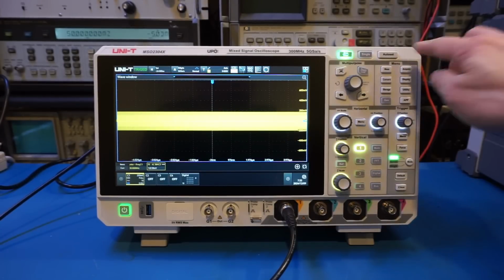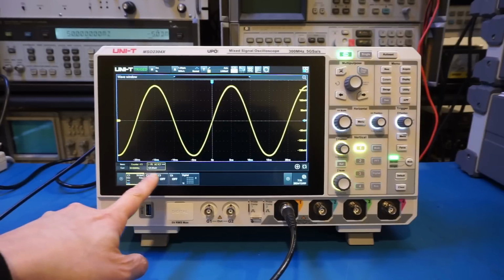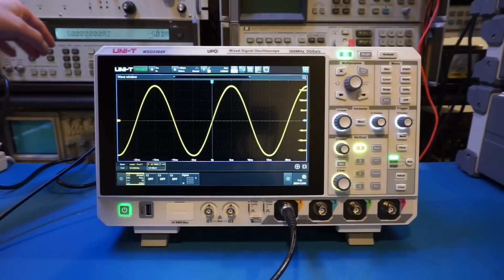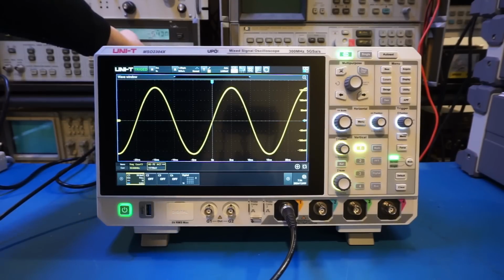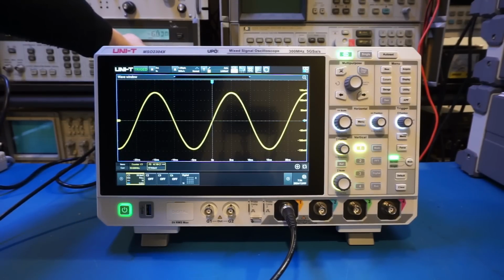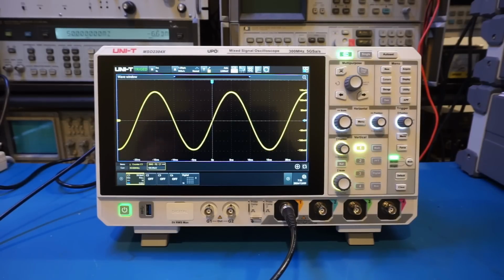Let's actually acquire the signal first. And also you can see right now it's at 121 millivolts. Let's actually change the attenuation a little bit so that we can get roughly 100 millivolts. The reason I chose 100 millivolts is because we can identify the 3 dB bandwidth more easily. And when we drop to roughly 70.1 millivolts, that's where the 3 dB bandwidth is. So let me right now increase the frequency and let's observe the amplitude.